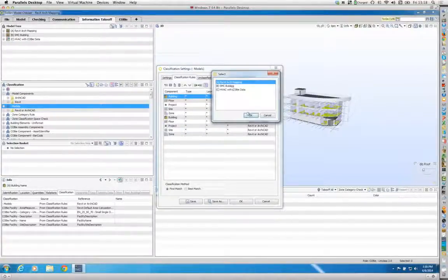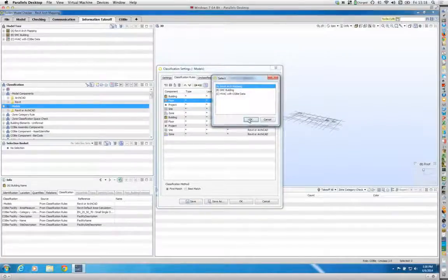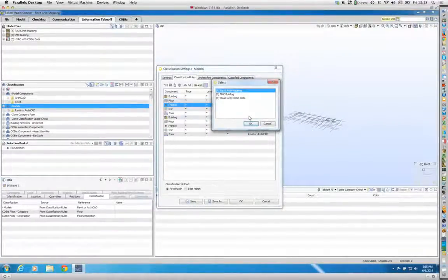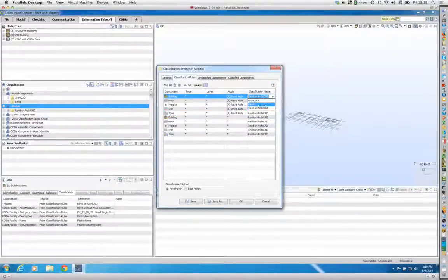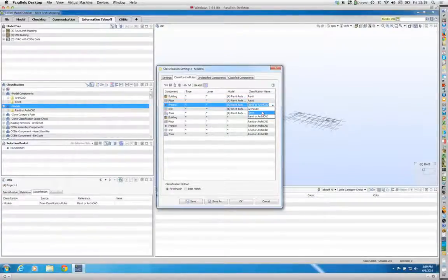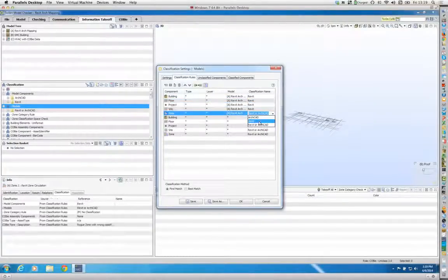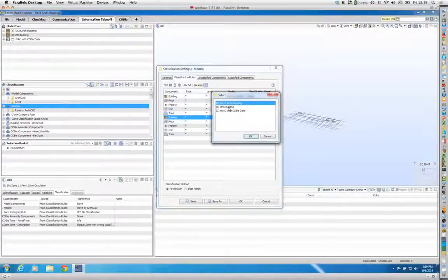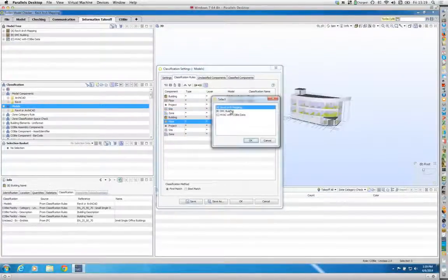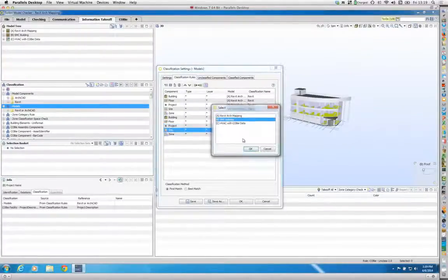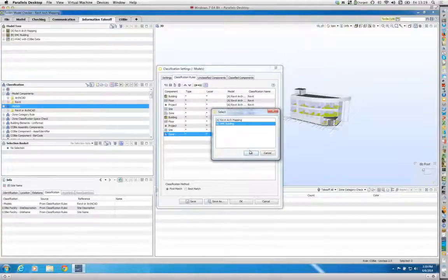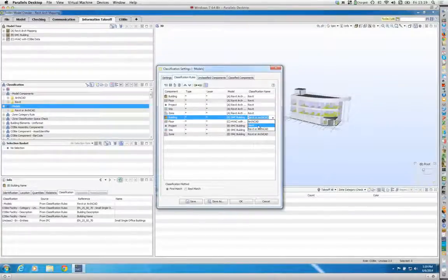So if I go into the list, here's the architectural Revit model. So we just go and select the model for each of those container fields. And so we've got them for the container fields. We'll just change the name now to Revit. And then in this one here, we'll select the SMC building, and you just go down. So this is our ArchiCAD model, and you go down to there, and SMC building. You notice that there's no HVAC listing on the zone one, because they're not in the HVAC model.